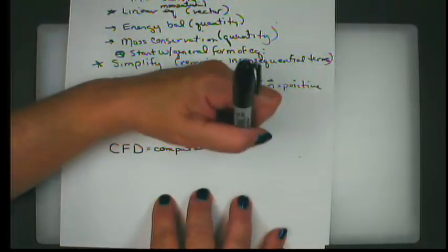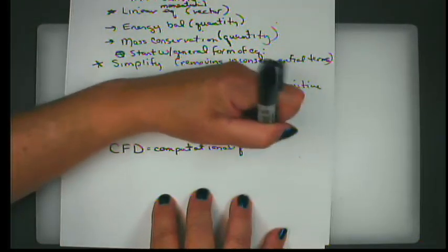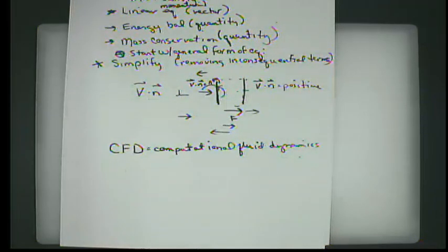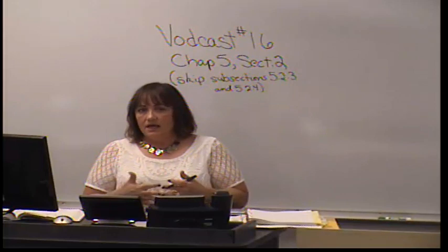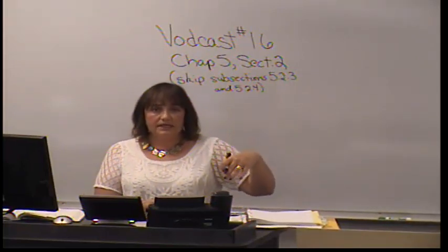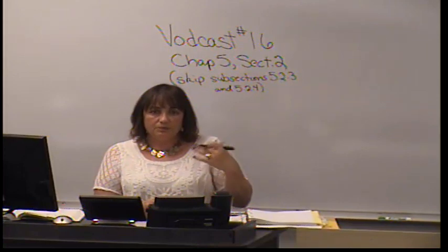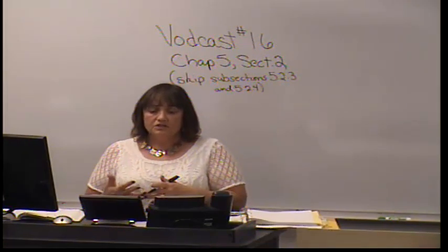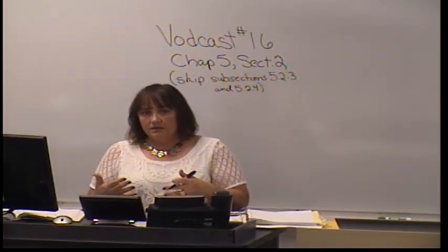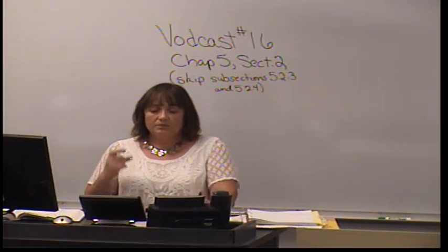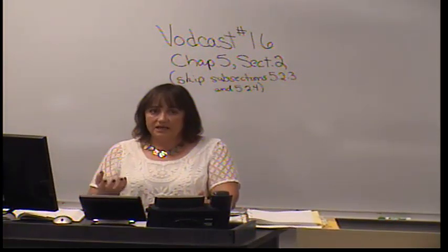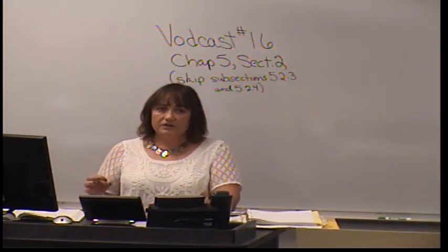And computational fluid dynamics often involves an equation called the Navier-Stokes equation that we will get into later, but computational fluid dynamics is really taking groups or classes of equations and solving them for particular instances. And because the math in fluid dynamics tends very often to be unsolvable, this is still an area where research is occurring. So we have other ways of attacking equations that are not analytically solvable, but at this stage of the game, eliminating or simplifying the terms that can be eliminated or simplified is very important. So it requires a certain amount of engineering analysis.